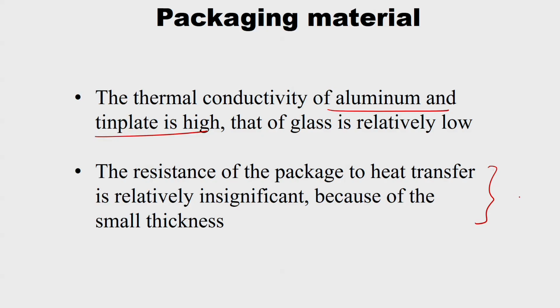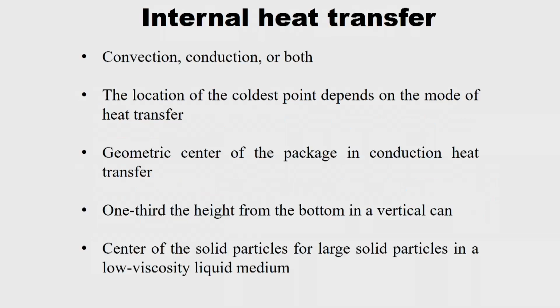And most of the time this heat transfer resistance is negligible due to the small thickness. The thickness of the wall is so minimal, so there will not be any appreciable heat transfer resistance. So, normally it is negligible. And then internal heat transfer. Internal heat transfer happens in two ways. One is conduction, another is convection. Sometimes both happen. If you have a liquid food with solid food particles, then through the liquid it is convection, and in the solid food particle it is conduction, right.